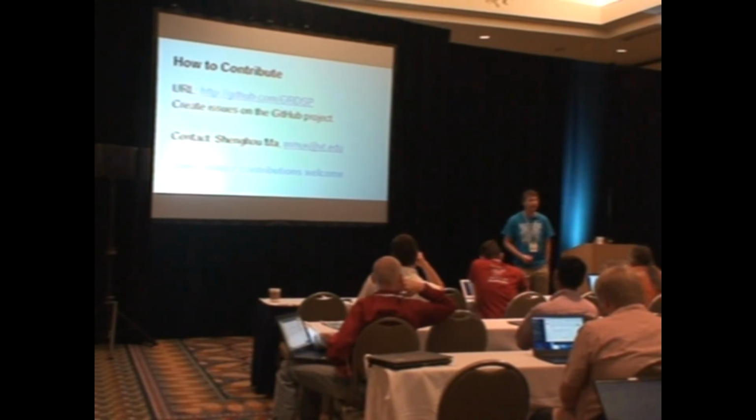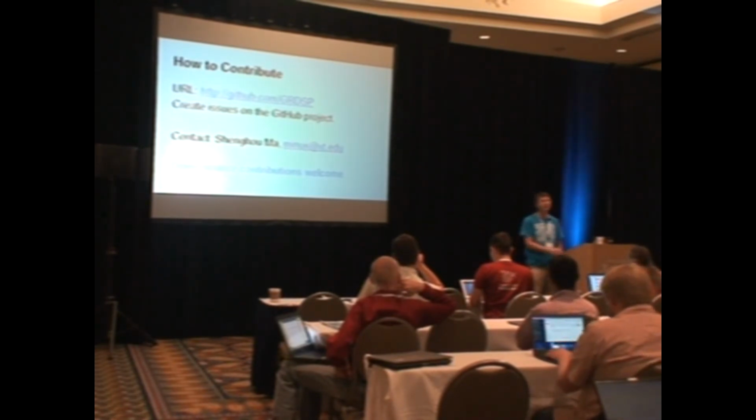Obviously, you have to know about that and pay attention, but basically you worry about that at the digitizer level. One of the reasons software-defined radio is hard is people will create a flow graph and won't pay attention to the gains, and they'll immediately drive things nonlinear and nothing will make any sense. So yes, there are important real-world issues that need to be dealt with.